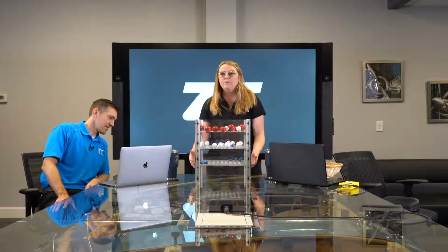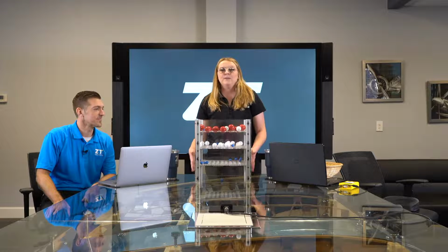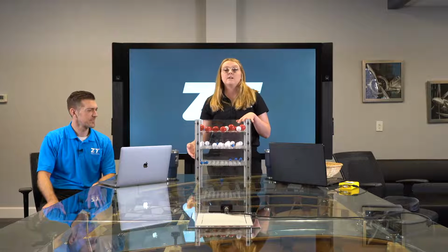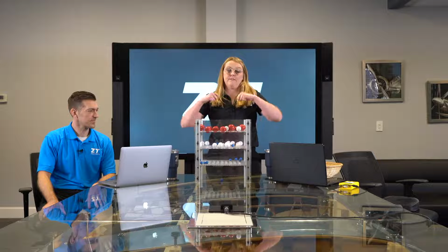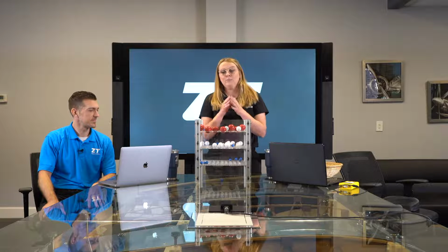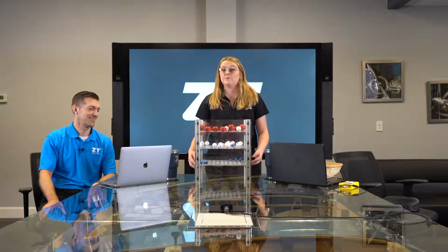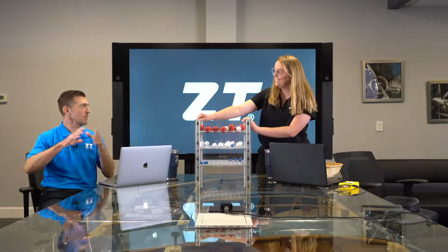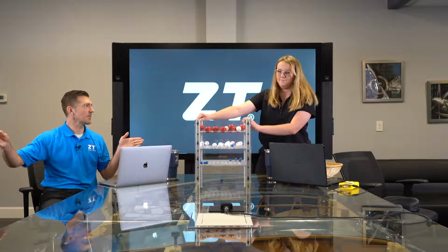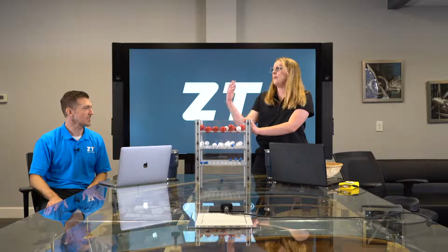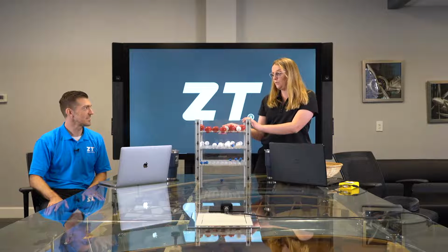We made a couple openings in this bottom, and that is to represent if you have any openings, say your shield doesn't go end to end, or what I see commonly with like a foil shield, if it's in a flexing application and kind of breaks down and makes a crack, now you have an opening and that interference is going to find its way in. Yeah, it's real good. It really demonstrates how important it is to shield as much of your cable as possible. Make sure it has a complete coverage around the item that you're shielding. And to choose the right material for what you've got going on.